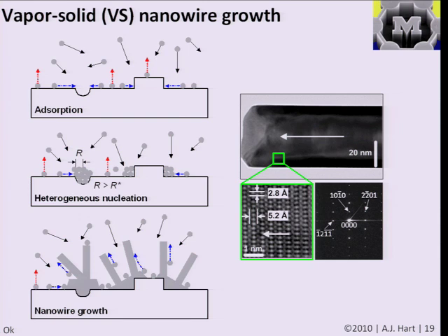So if I, for example, stop the picture here, I would have this picture that I just had on the previous slide, a flat substrate or a substrate that looks flat from the top with a whole bunch of clusters of different sizes. And then I would have nanoparticles on a substrate. But what happens in this case is for certain materials, if I continue the process and I have a material that has a crystal structure that will grow more favorably in one direction than the other, and I control the pressure and the temperature of the process to enable the growth to happen slowly, I might indeed form nanowires of that material from the substrate upward.